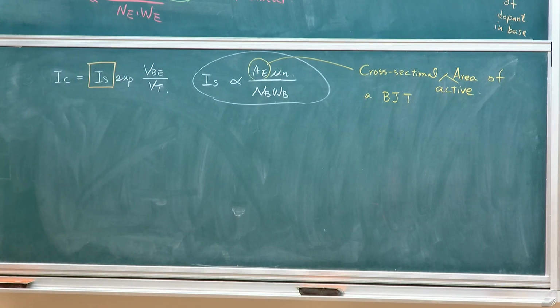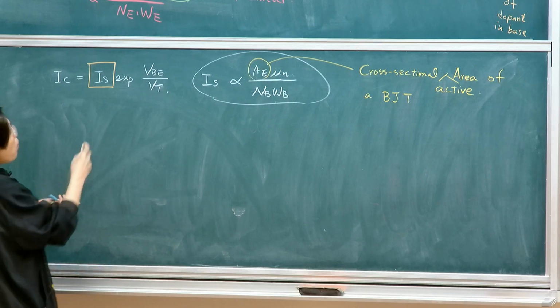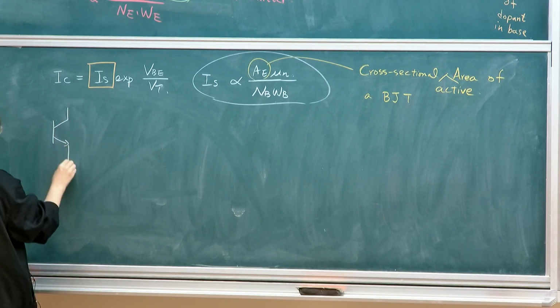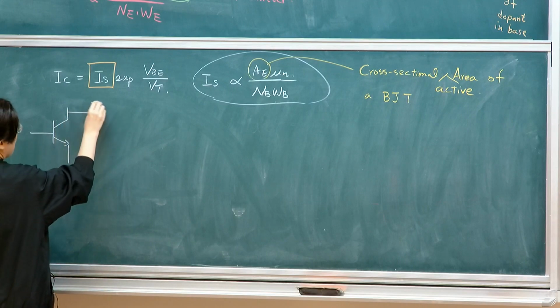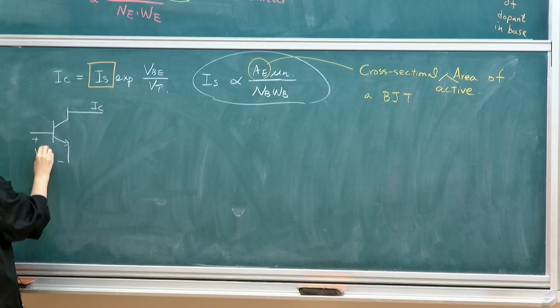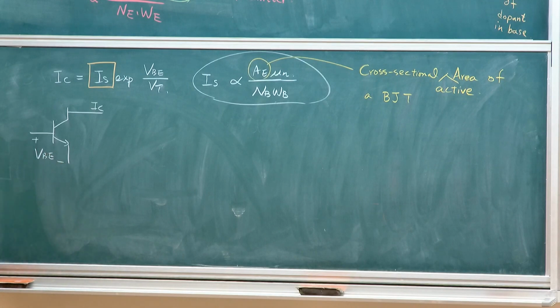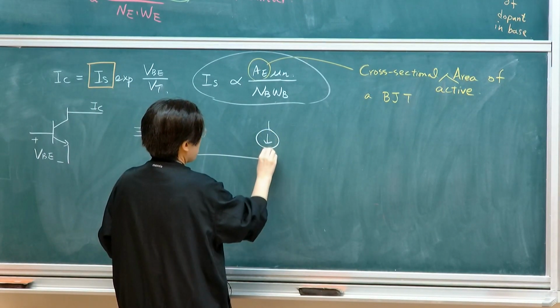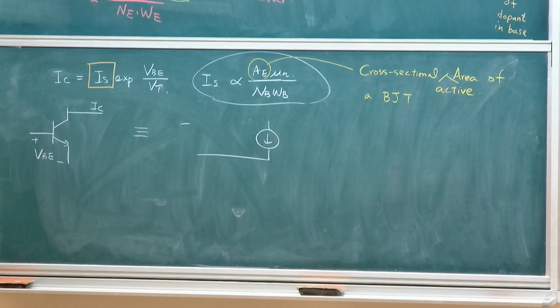Okay? So what does this allow us to establish? If I want to construct my bipolar junction transistor model, I want to look at the output terminal, which is IC, and the input control. So based on this, I could establish a sub-circuit model. If you use circuit theory, it will look something like this. I already established what we started with on our wish list, which is a voltage controlled current source.